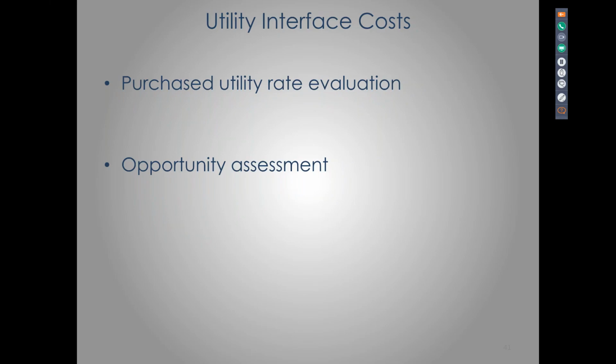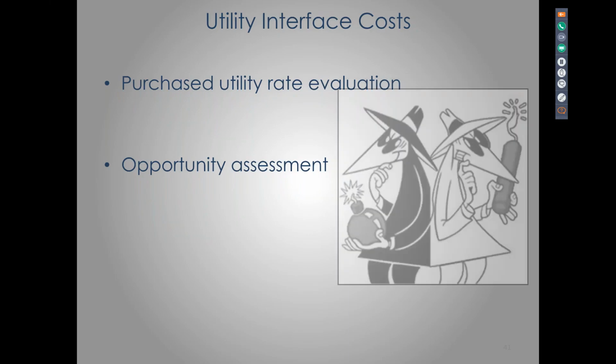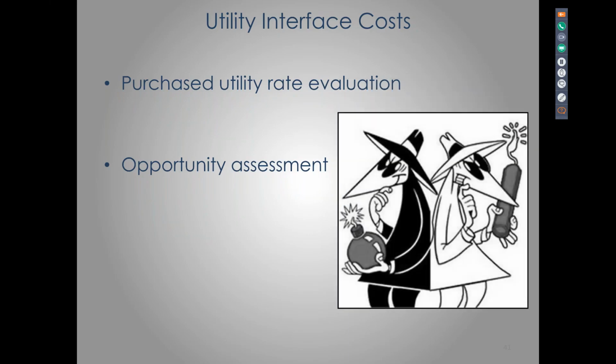At one time, our utility was charging a whole lot for what they called a ratchet demand clause. So the university came up with a clever way to avoid the ratchet demand. That's something we call the red line, saving $500,000 a year. Well, then the utility comes up with another thing they can gig us for $500,000 a year. And sure enough, we figured out how to put in capacitor banks to solve that problem. So it's a little bit like a spy versus spy kind of thing. Utility changes the rate, we figure out what the deal is, and then possibly make some adjustments in operation.